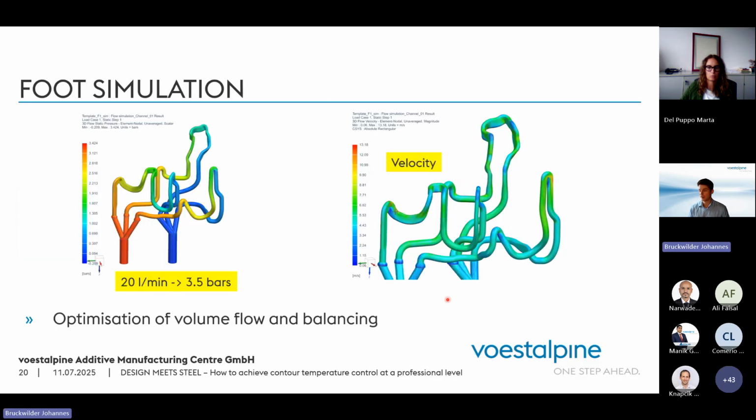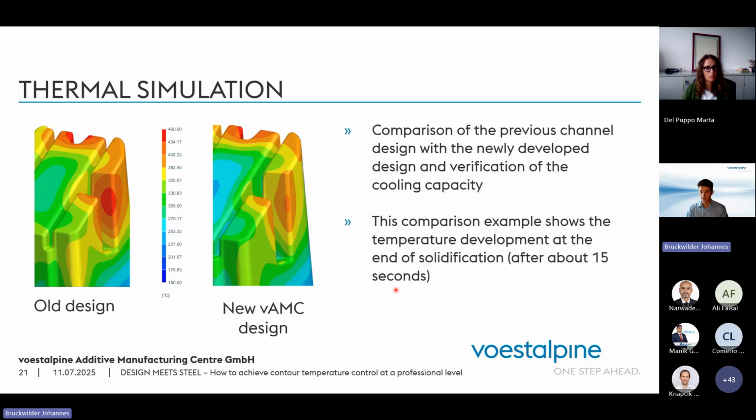If we design those channels and we do a parallel channel design, here you see the parallel channel design, it's always important that the channels are balanced. That means that in every one of those 3 channels runs the same water or oil. It's important that not just one gets all the water or all the oil and the other 2 are neglected. Here you see the velocity. This is a typical flow analysis that we do to balance those channels.